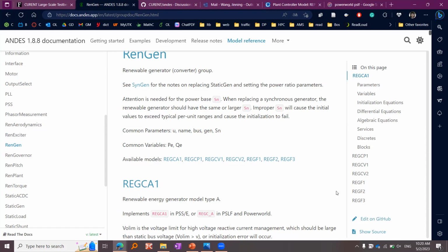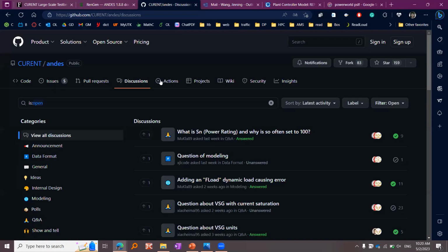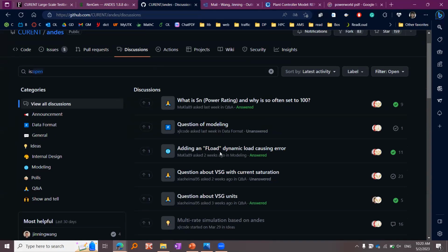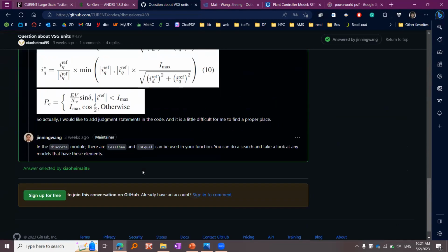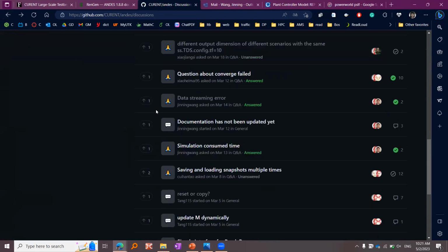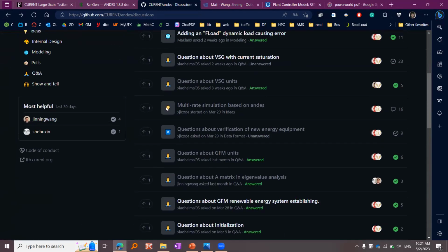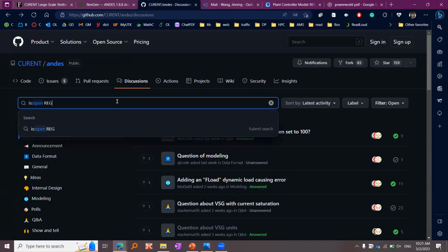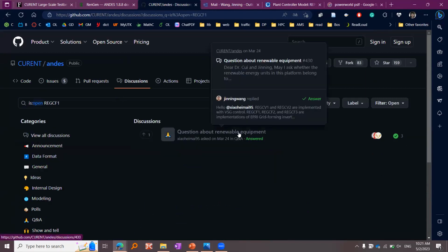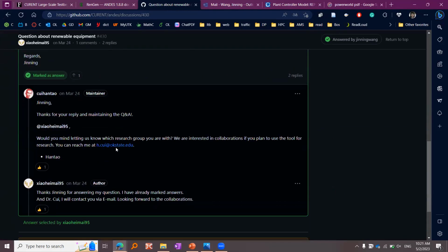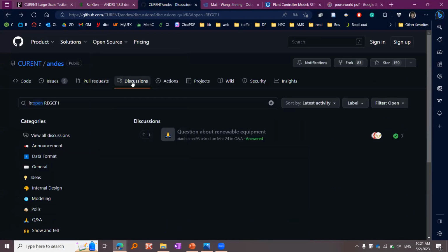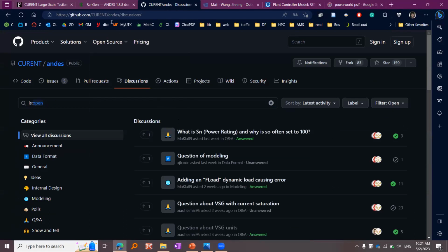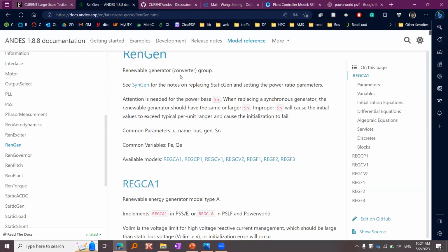The most important thing, whether it's grid forming or grid following, is that these are not detailed models of the power electronics. It's nothing about the switching, nothing about how it's actually generating the signal. It's only about the things that we care about on the grid, which is voltage controls, real and reactive power outputs, and frequency control. So you can do artificial inertia, and lots of different functions, but the way we're going to model them has none of the detailed inner loops of the power electronics, because those are too fast. It's just the outer control loops.